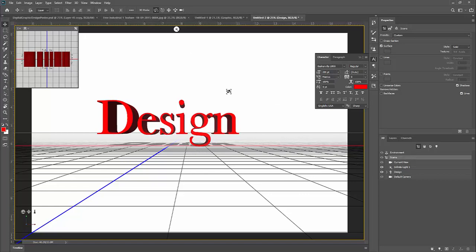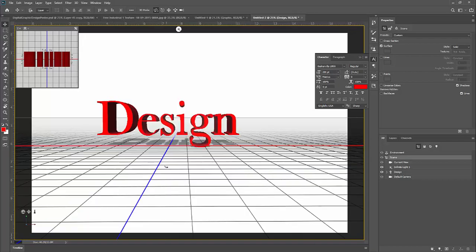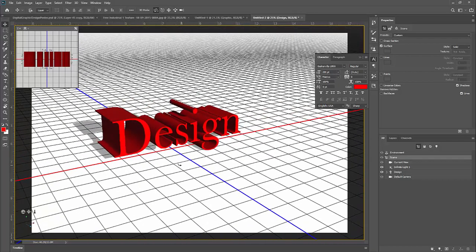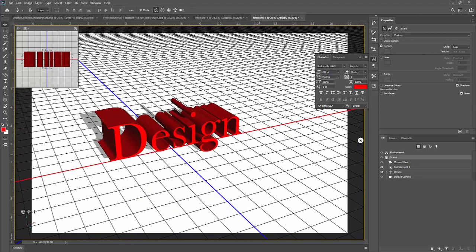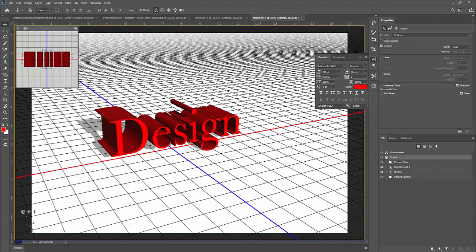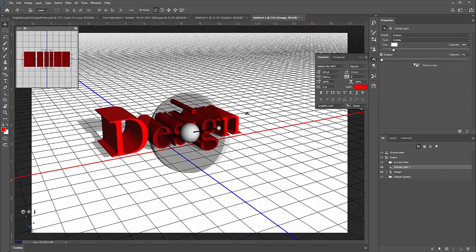So with this tool selected and scene selected, I can now rotate around and see my actual scene here, okay, in 3D space. I'm just left clicking with the mouse again, and I can rotate around and find a cool angle that I like. Once I do that, I can go back to the light. Again, I can click on the light here, and now I can pivot the light and move it around, rotate it however I want.